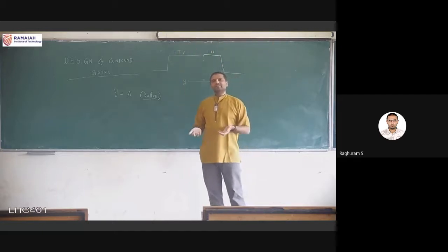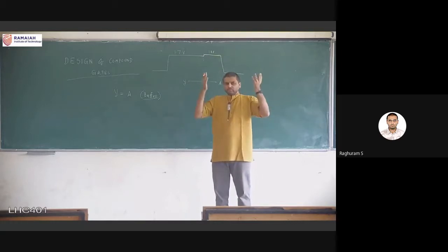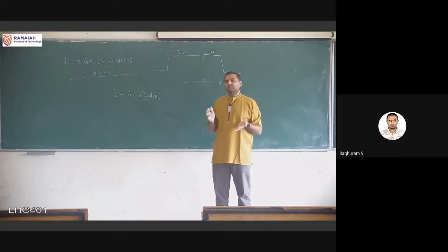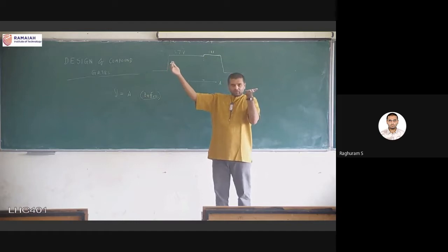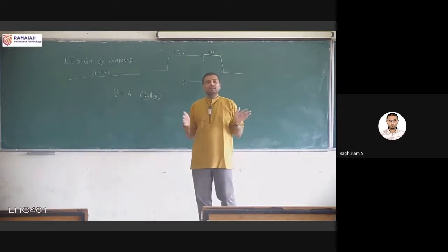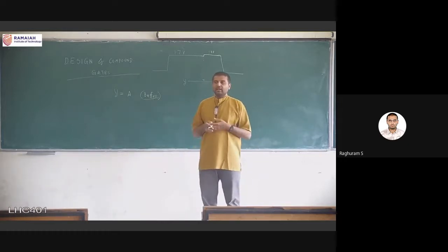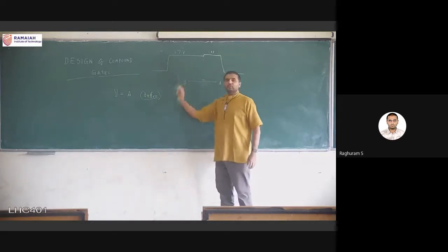But if you look at VLSI circuits, the separation between wires is very, very low. So even though they are sitting on the silicon substrate, even though they are insulated, because the separation is so low, they can talk through the substrate. So if some neighboring circuit, some change is happening, my wire, which is supposed to be at a constant value, can get affected. It can get pulled up or pulled down, mainly because they are all interconnected capacitively. And that is the reason why this could go down from 1.8 to 1.7.